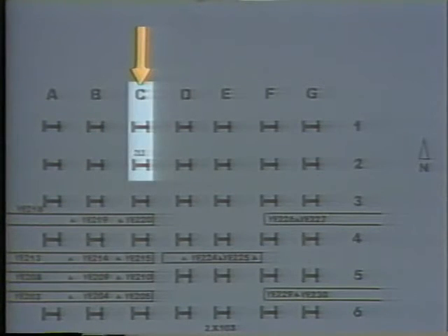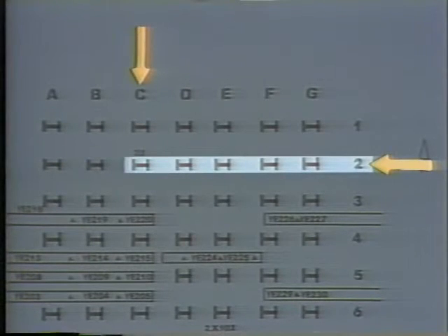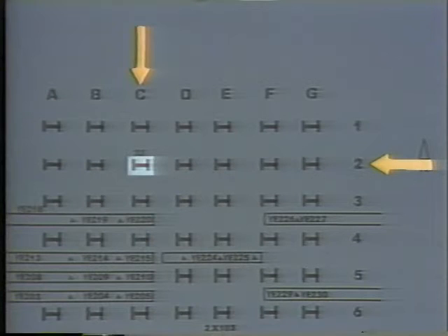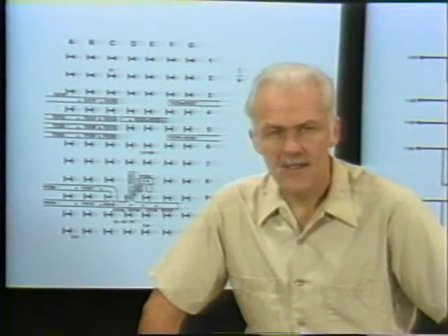Next, let's follow a straight line down the diagram until we're directly in line with the number 2. Here's the symbol for a column. As you can see, the column symbol is not identified on the diagram, but we know this is column number C2 because we followed the grid identification correctly. The columns in most plants are marked so that when you determine what column you're looking for, you can find it.